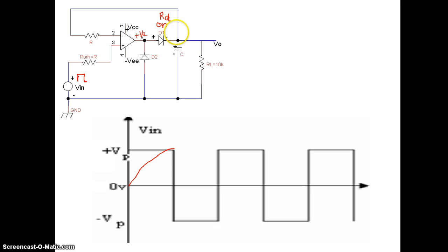And remember, the charging time of the capacitor, say I write it as TC, is given through this on resistance of the diode, that is RD into C. Remember that the period of the square wave is say T. Now this TC is very much less than T by 10, that is, only one tenth of the period it will take to charge.